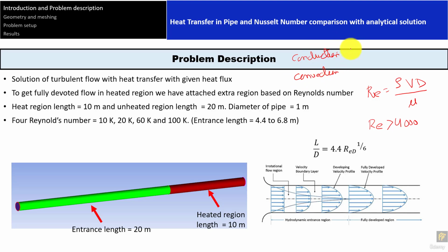So if I write down here the laws, for conduction, it is Fourier's law of conduction, that is Q is equal to minus K A delta T by delta X. This minus sign is for the direction of the heat transfer, to make it correct. And area is the normal surface area perpendicular to the direction of the heat transfer.